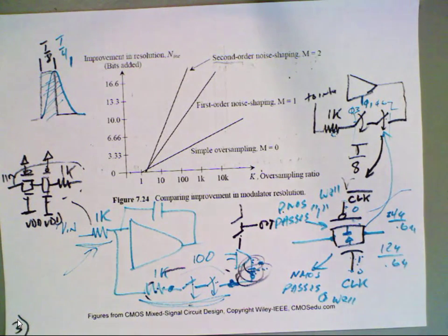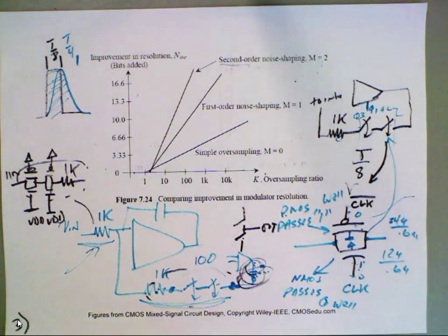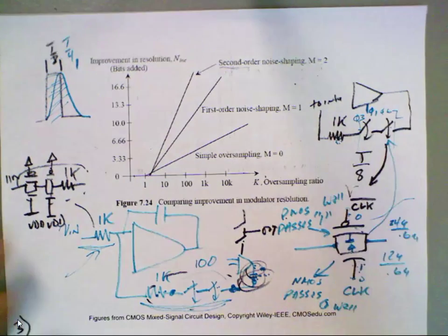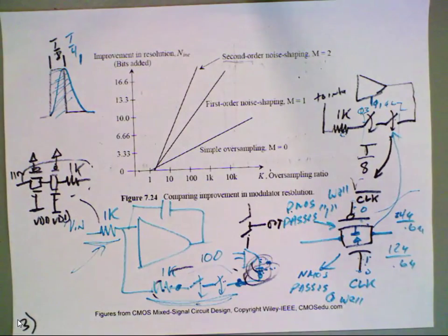It's going to vary, because if you overdrive the inputs, it's going to switch faster than if they're real close together. Then it shoots out the delay, and that's going to set your feedback time. And the problem is, it's always going to drive the inputs of the comparator. That's the whole point of the feedback loop, drive them together.